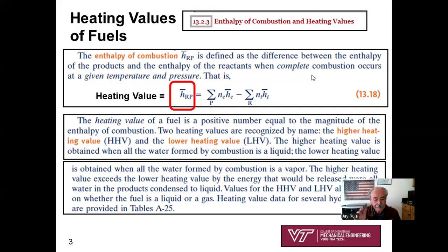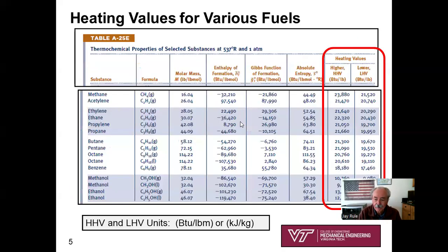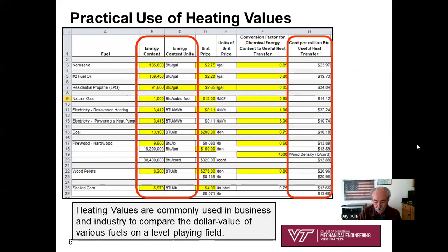But do recognize that this heating value term, with complete combustion, not saying anything about excess air or oxygen only or burning with air, gives you a good, quick, and dirty method for getting tabulated heating values, so that you as an engineer might continue on to do an economic study of lots of different fuels and not go into that Chapter 13 detailed analysis.